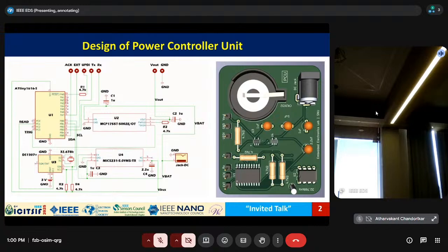This other voltage regulator IC consumes 1 to 5 microampere, which is negligible. But the output driving capacity of this low dropout voltage regulator IC is that it can support only 10 milliampere output current. So with this you can run the sensor and other stuff, but you cannot run the Arduino or the STM boards because those require high current.